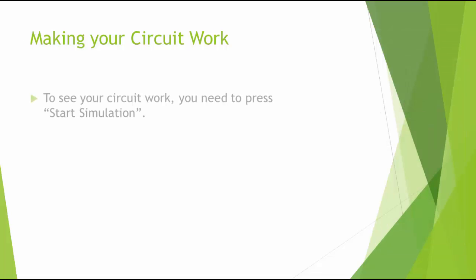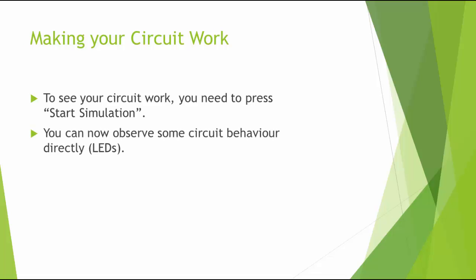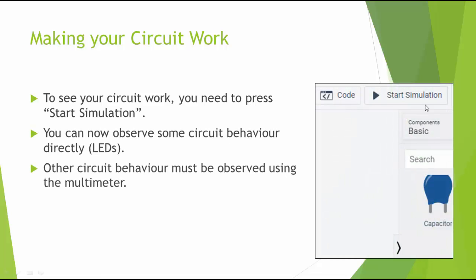Now, once you've built that circuit, you'd expect the LED to light up immediately. In fact, TinkerCAD isn't set up that way. When you want to see the circuit work, you need to press Start Simulation. So there's a button on the right-hand side. When you start the simulation, it's the equivalent of connecting power to your circuit, assuming that you have a power source as part of it.